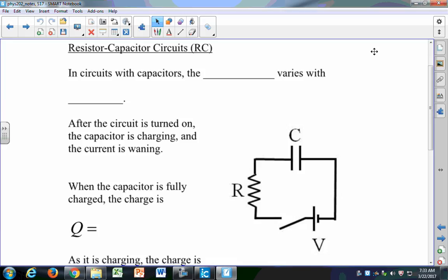So we'll look at the exponential growth and decay and just learn, you'll need to practice on how to solve those for particular things. Learn how we characterize these growth and decay curves. When I have an exponential growth curve or when I have an exponential decay curve, how we characterize those by the time constant and how we solve for particular values in that, and just what they look like. As I said, this will be important for other circuits that we'll look at later, LRC and LC circuits, because they'll operate in a similar way.